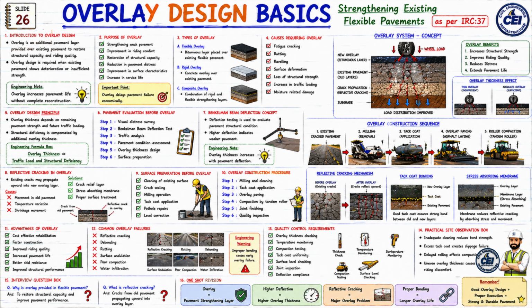1. Practical site observation box. Inadequate cleaning reduces bond strength. Excess tack coat creates slippage failure. Delayed rolling affects compaction quality. Uneven overlay thickness causes riding discomfort. And these observations are frequently seen during field inspection.